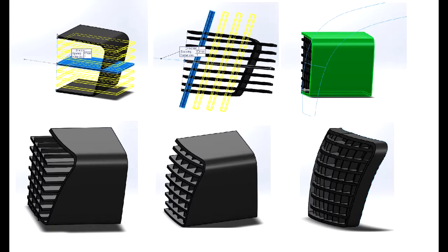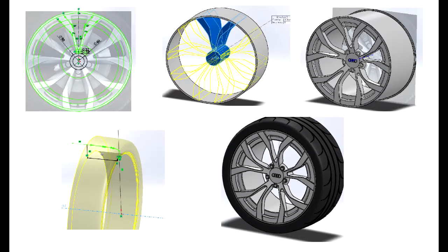Another useful technique I used is incorporating linear patterning and offset surfacing to cut and create the front grille and wheel with a simple pattern. The offset surface helps by allowing you to use the cut with surface tool and make complex cuts.